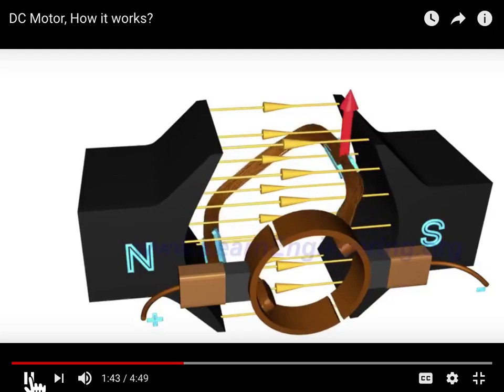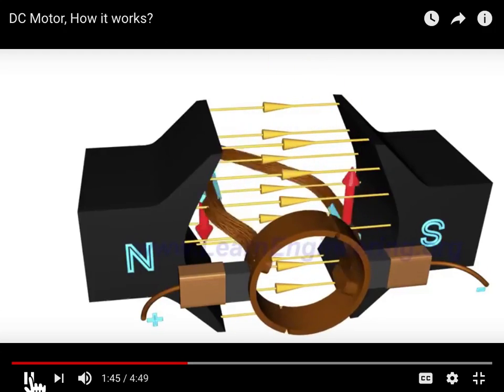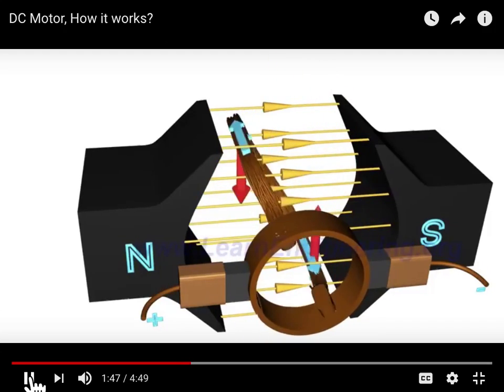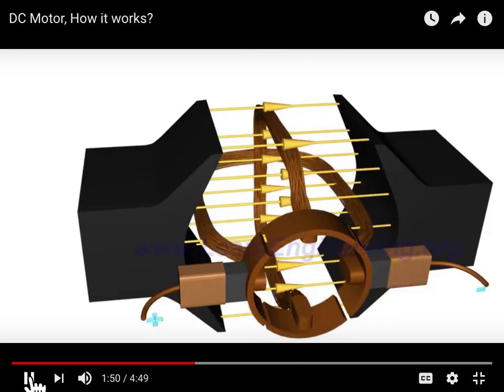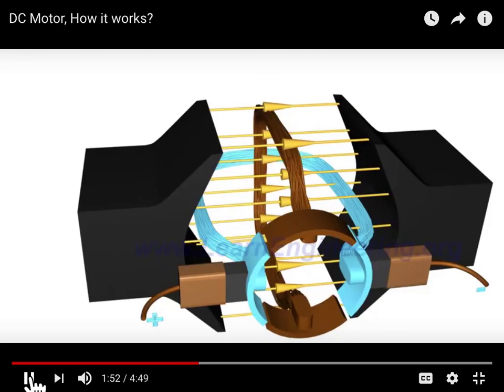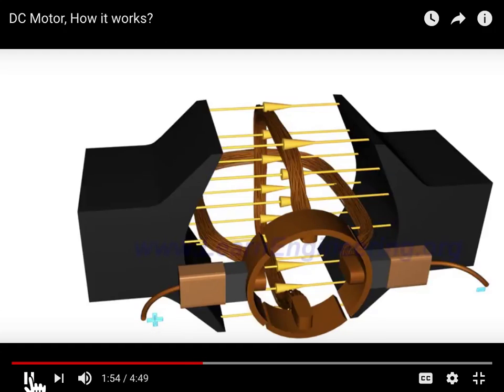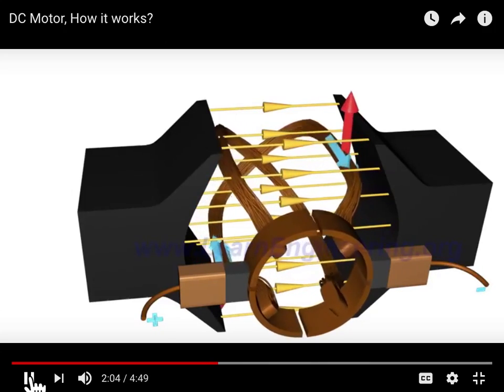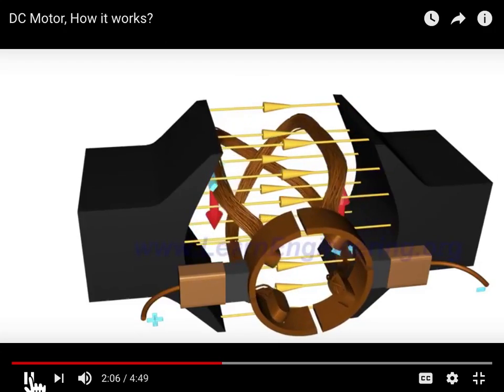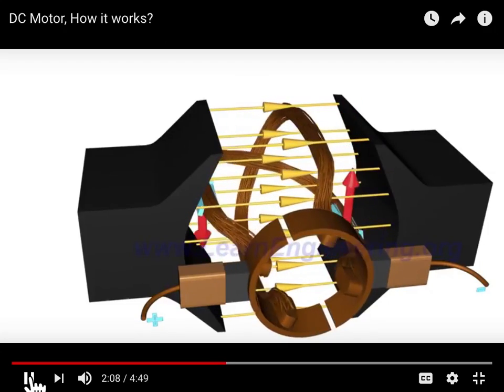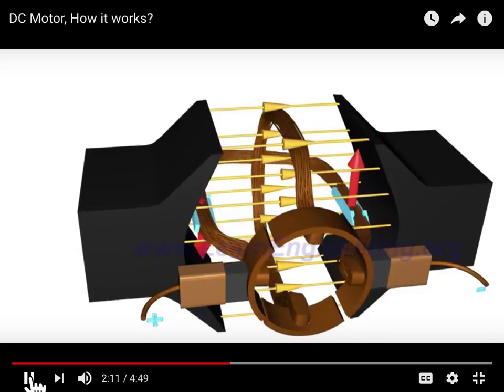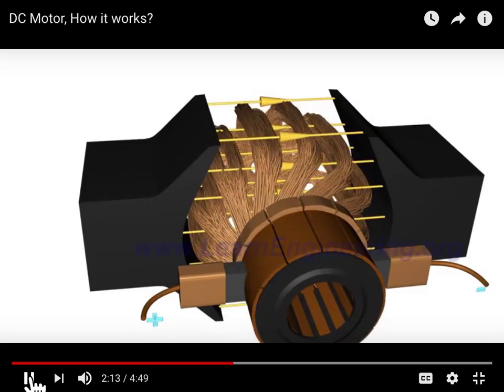This is what it would look like. Here is the trick to overcoming this problem. Add one more loop to the rotor, with a separate commutator pair for it. In this arrangement, when the first loop is in the vertical position, the second loop will be connected to the power source. So a motive force is always present in the system. Moreover, the more such loops, the smoother will be the motor rotation.